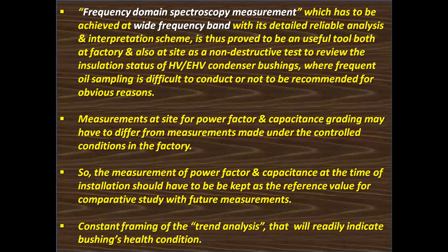Measurements at site for power factor and capacitance grading may have to differ from measurements made under the controlled conditions in the factory. It is just because the electrical noise at site is much more, whereas in the factory state, the environmental electrical noise should be arranged to minimum level.